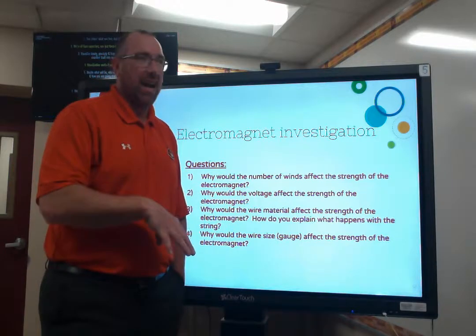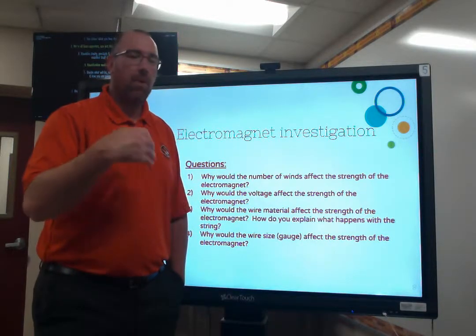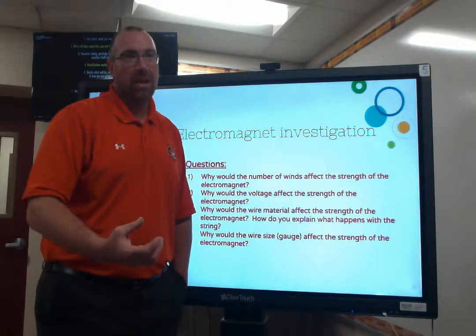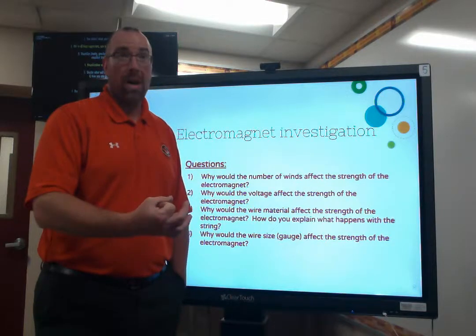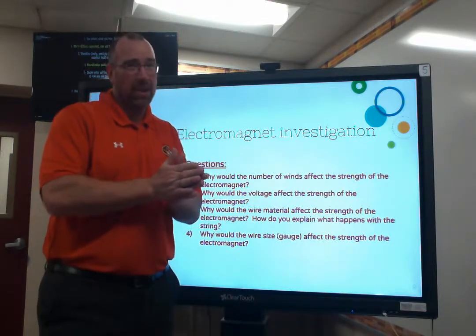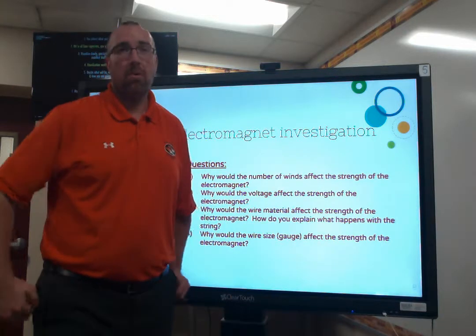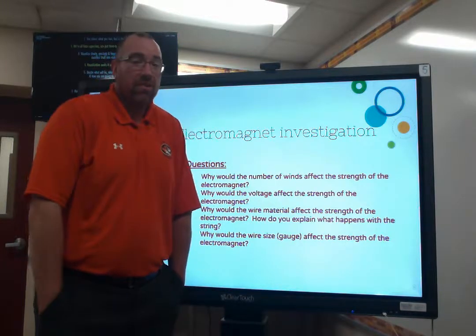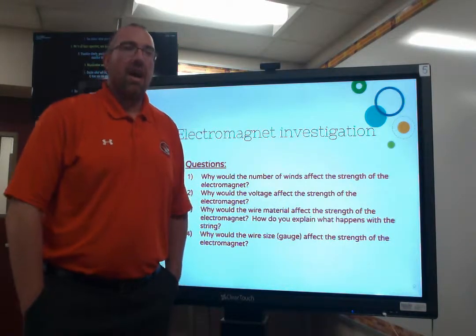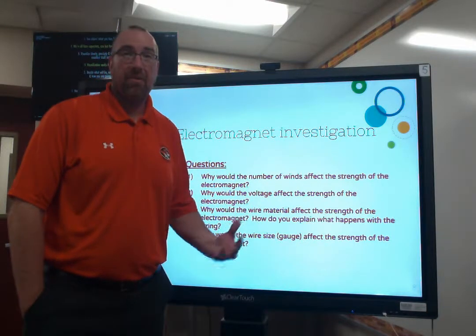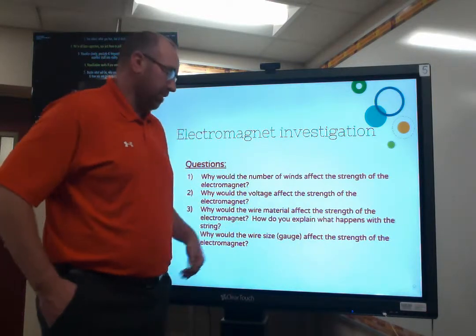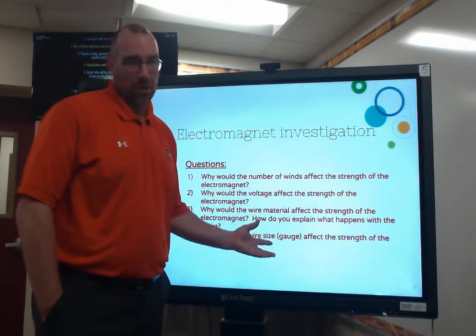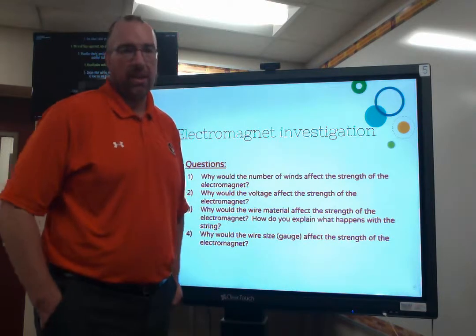I mean, if you're wiring a house and you don't know how much current is going to flow through a circuit and you use too small a gauge of wire, you might end up burning the house down, because smaller wire means more resistance, which means more heat generation, and the wire will burn through or could get hot enough to set something around it on fire. So it's very, very important to understand what gauge of wire you need for a particular current running through a circuit. So bigger gauge, more current, less resistance, stronger electric field, stronger electromagnet.